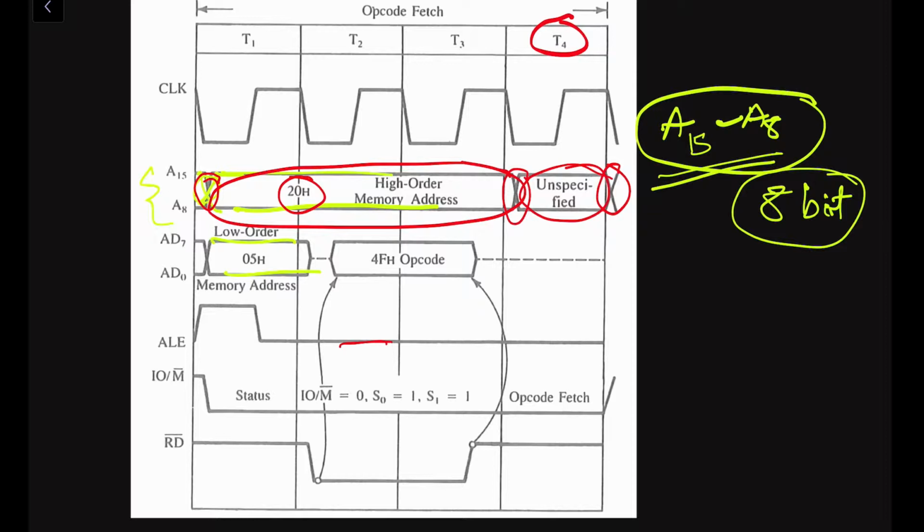Okay, so we have understood why there are two parallel lines in the case of the address and data lines, because we have multiple bits transmitted in parallel. Some bits may be low, some bits may be high, so we represent them by two parallel lines. Now, the crossover lines indicate that a new byte of information is placed on the bus, and the dashed straight line indicates high impedance.